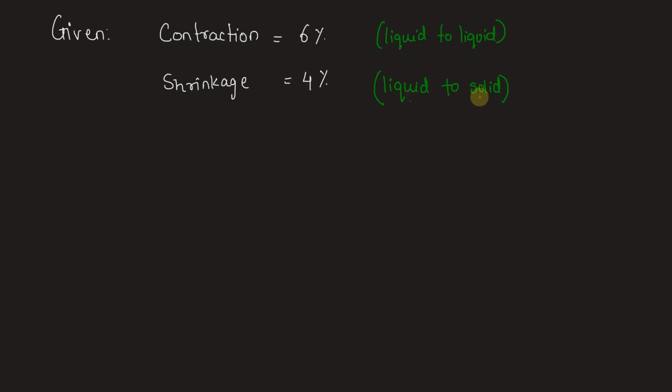So when we consider the decrease in volume, we will have to consider it in two stages. First stage being the decrease in volume due to solid contraction. Let the initial volume be Vi. So final volume after contraction will be VFC. And in the second stage, after volumetric shrinkage happens, let the final volume be VFS. So the final volume that we are looking for is the absolute final, that is after the shrinkage that happens.